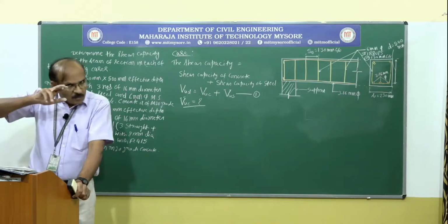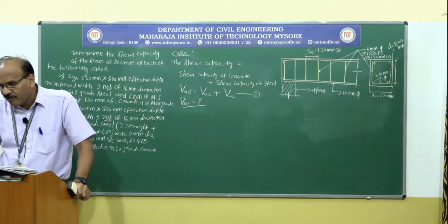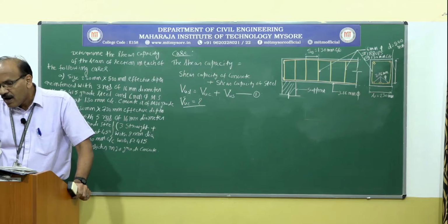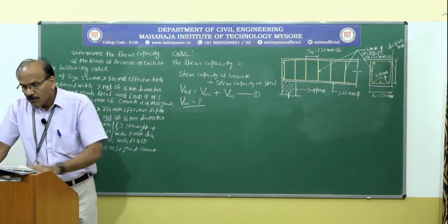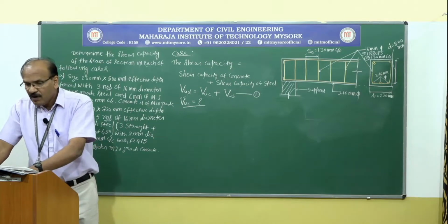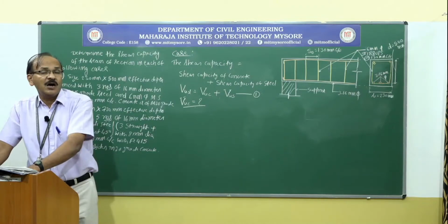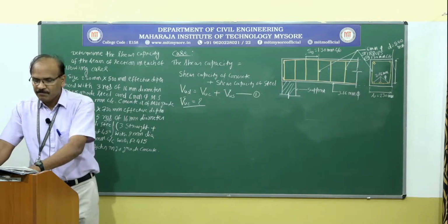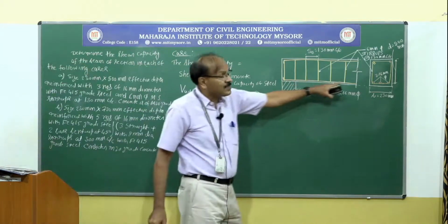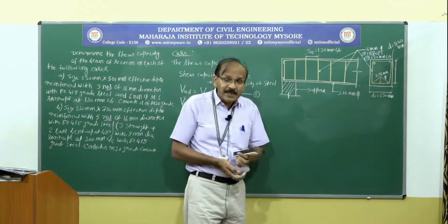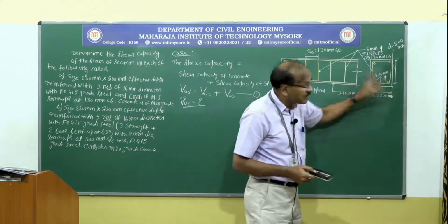Go horizontally along that line, and you see M15, M20, M25, etc., up to M40. For example, if you are using 0.75% of tension steel, here AS refers to the tension steel, because the shear capacity of concrete depends on the percentage of this tension steel.